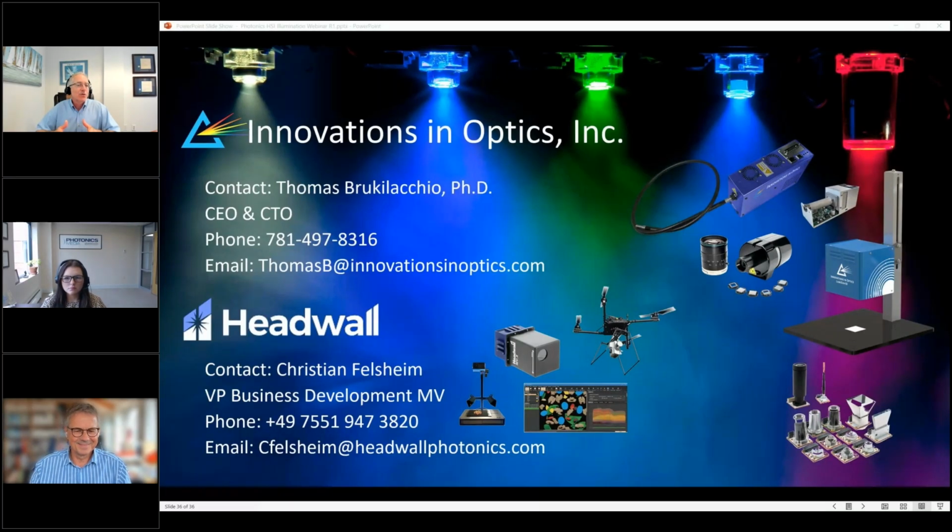But in general, as mentioned earlier, when you're looking at something of relatively small size, then different geometries can be used, and very typically it's a camera looking straight down, normal to the conveyor belt, with a 45-degree, maybe plus or minus, on the illumination. That gives very good uniformity. The object size is small, so you don't need as great a depth of illumination.